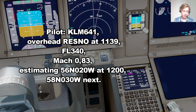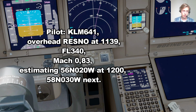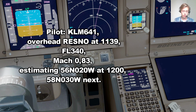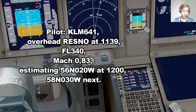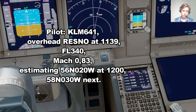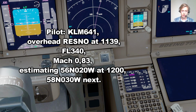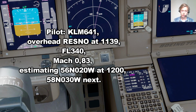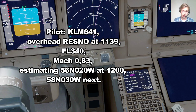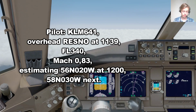Okay, so that's it, right? You report the waypoint you're over at, so in this case Resno, at what time? 1139 Zulu. Your flight level that you're at, your max speed, then the next waypoint, which is 56 north 20 west at 1200 Zulu, and then the waypoint after that, just mention that waypoint, so 58 north 30 west, okay? So that's the way you do a position report.